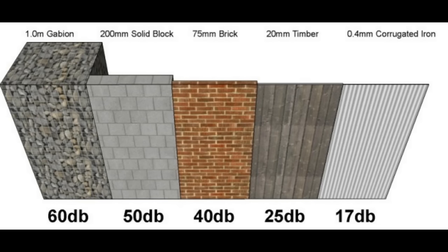Many different materials and thicknesses of materials have been given what's called NRC, Noise Reduction Coefficient, or STC, sound transmission class numbers, to give you some idea of how much noise a particular product can stop or how much it will absorb.